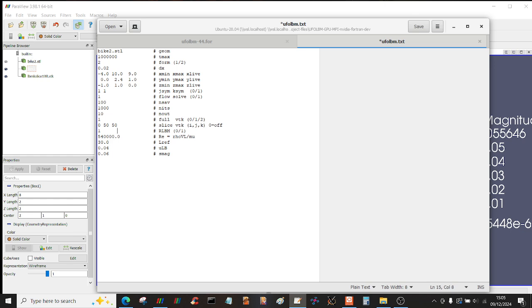So that's for the slices. And the rest are the actual solver parameters. 1 here is for the regularized lattice Boltzmann method. So I would leave that at 1 now, because now that it's working for regularized lattice Boltzmann, which means high Reynolds numbers, there's not really any need to change that. But the original formulation is set to 0.